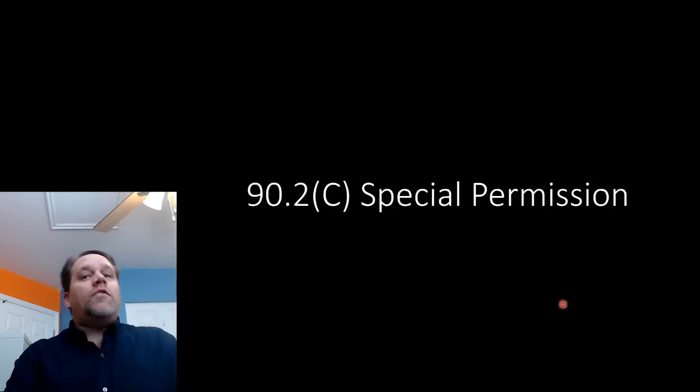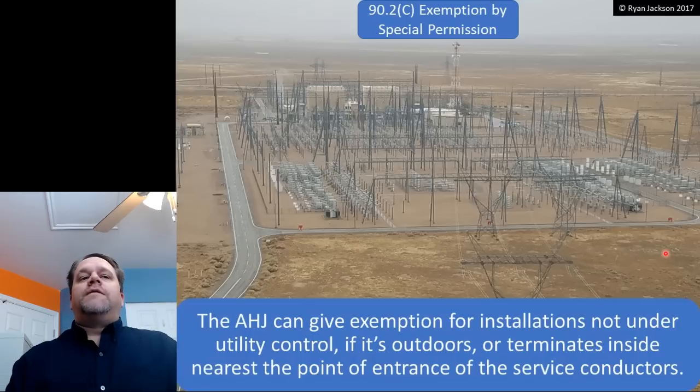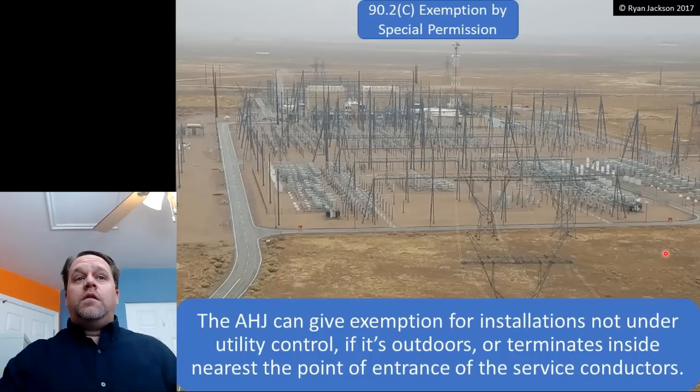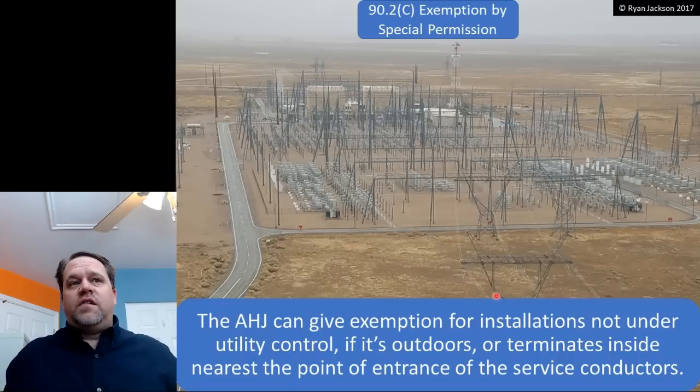However, we do have 90.2(C), and this is important. Special permission. The AHJ can give exemption for installations that are not under utility control, if it's outdoors or if it terminates inside nearest the point of entrance of the service conductors. Looking at this photograph, yeah, this looks like utility stuff, but it doesn't have to be. This could be at my buddy's chemical plant. They have a switch yard like this that is absolutely massive.